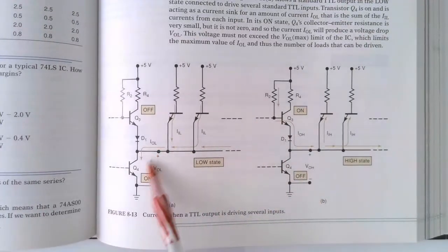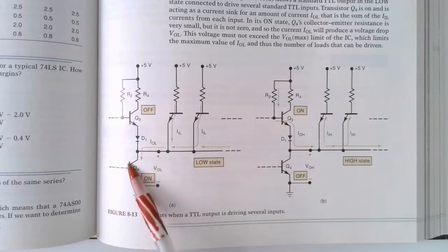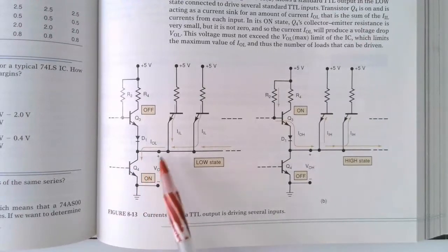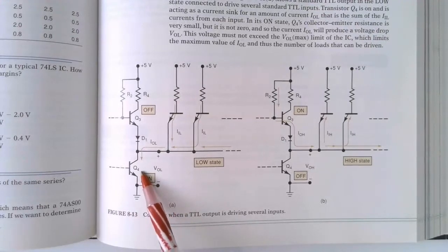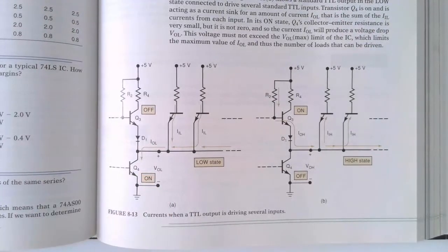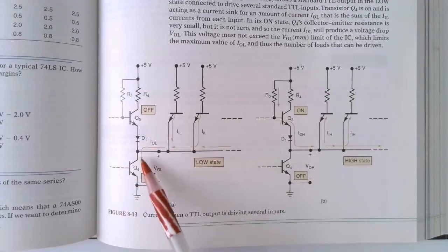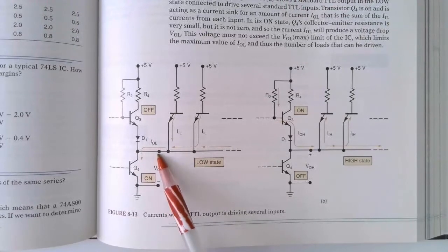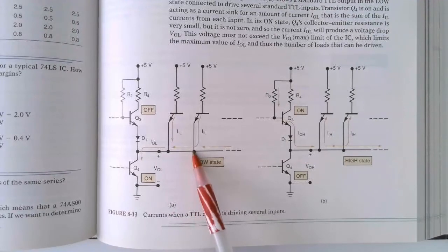Now, interestingly, typically these TTL devices can sink a lot more current than they can source. And that's a lot of the times why we'll be talking about negative logic and inverted inputs and outputs. They're much more common, and that's because they typically can connect to more devices. What this is showing on the right is the output of a TTL device, and then this is an input where we have multiple devices connected. I'll draw a logic diagram for this in a moment.